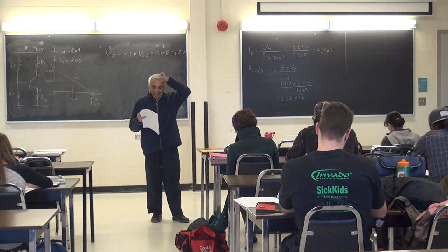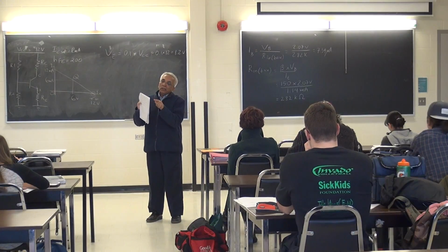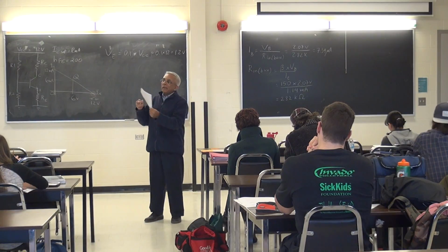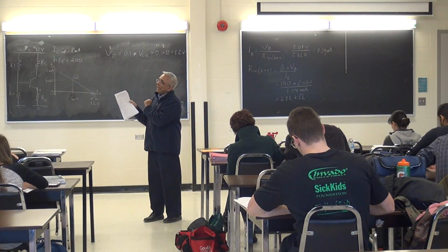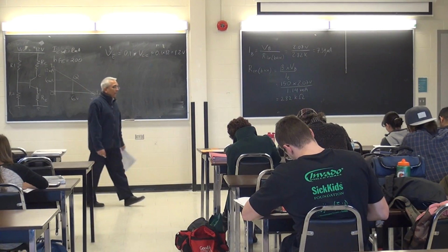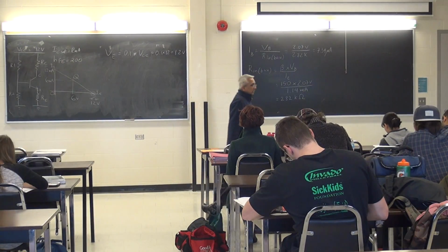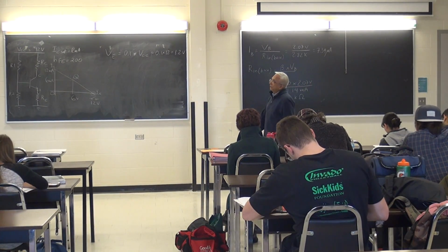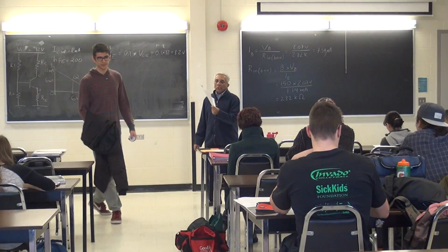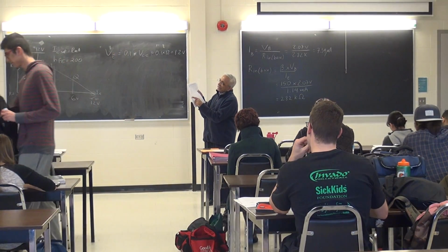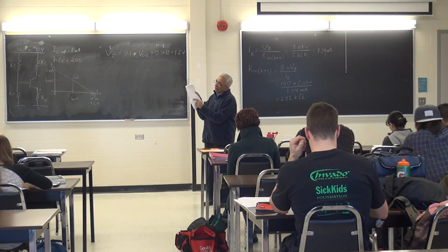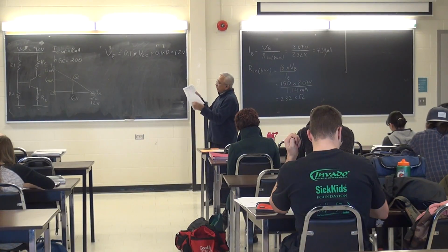The idea is that these two rules of thumb apply for stiff circuits. So write the note stiff circuit beside the rule of thumb. Where it says rule of thumb, on the right side indicate for stiff circuits. These rules of thumb apply for stiff circuits. Okay. So, on your notes, the first one is cutoff. VCC, how much? 12. Saturation, how much? 12 milliamps. VE, 1.2 volts.